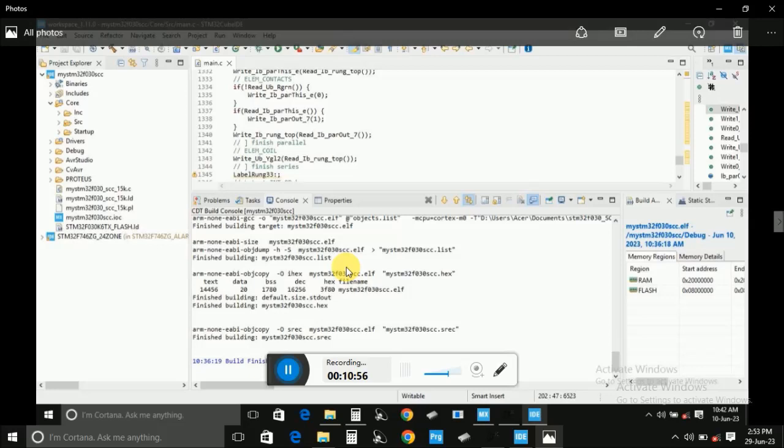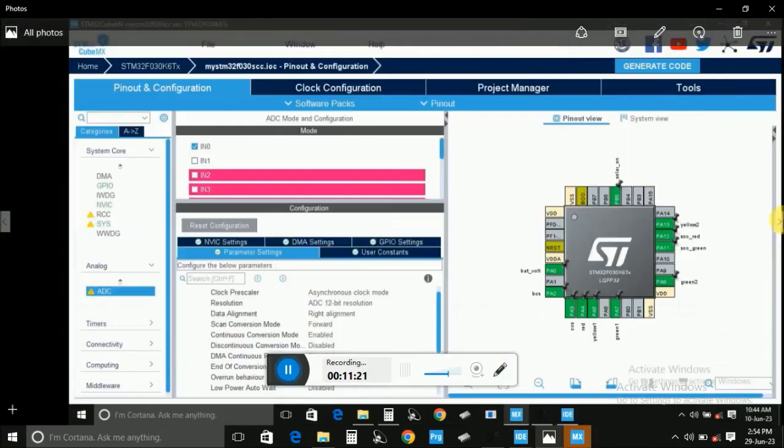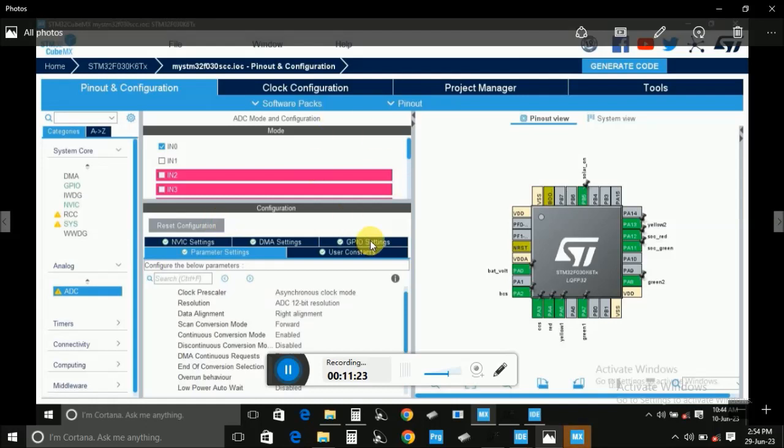Now here is the Cube IDE, and you can see the successful compiling of the file. You actually copy the C that the ldmicro produces, adjust it, and then you compile. I'll show you how you can adjust it, and I'll share with you the whole code. And then here is the CubeMX configuration that you do, and you can see there the IC and its pinout